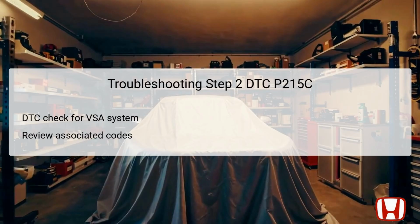The second troubleshooting step focuses on checking the Vehicle Stability Assist (VSA) system for related error codes. The VSA system plays a critical role in maintaining vehicle stability during cornering and slippery conditions, thus requiring close examination. Using the Honda Diagnostic System (HDS), technicians should check for specific DTCs related to the VSA system, such as C0030 for the magnetic encoder failure, or C0031 for left front wheel speed sensor failures.